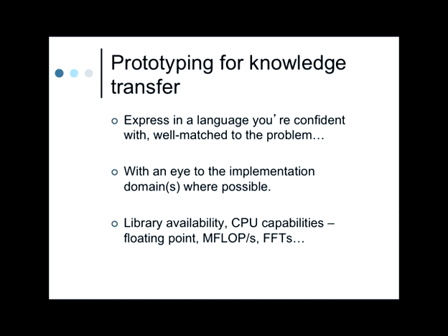Does the chip you're thinking about, or your customer might be thinking about, have floating point? This is stuff that you really need to be thinking about even when designing a prototype, because if you're heavily relying on FFTs and their hardware won't do FFTs, or they haven't allocated enough of the CPU time on the console they're doing to do audio stuff, then your prototype might not ever actually translate into something they can use.